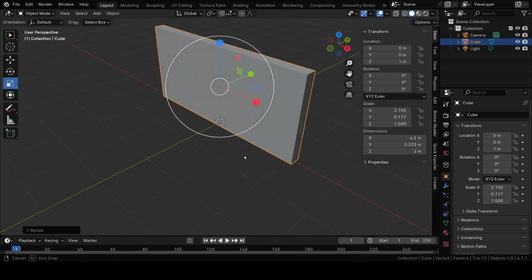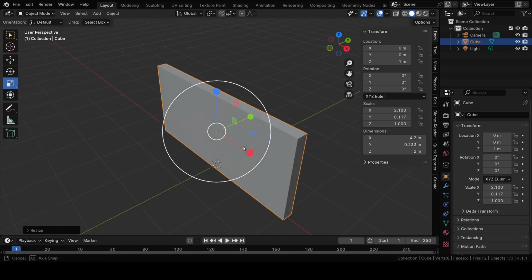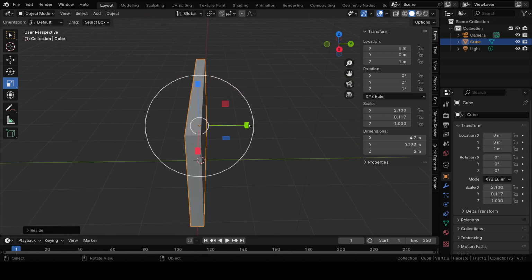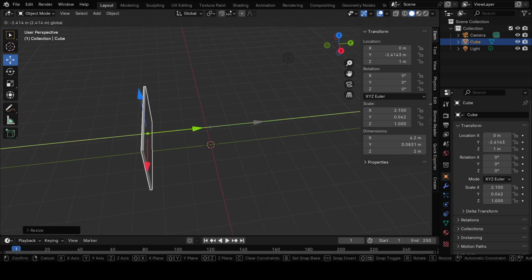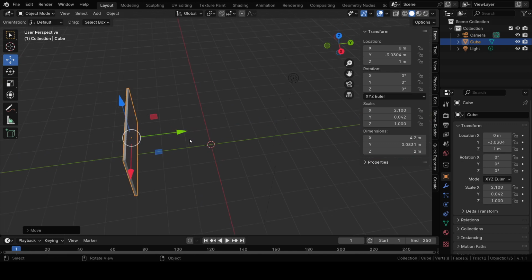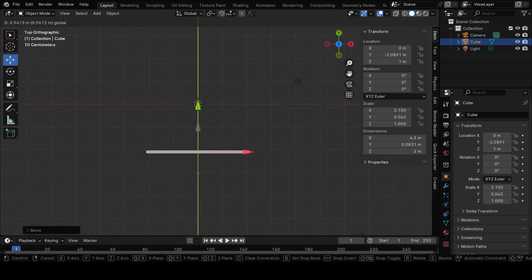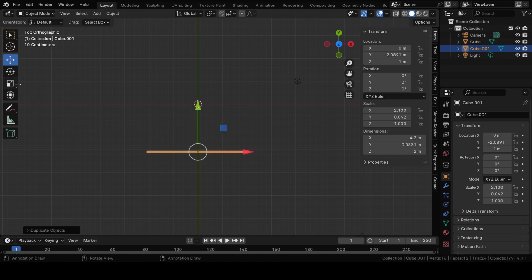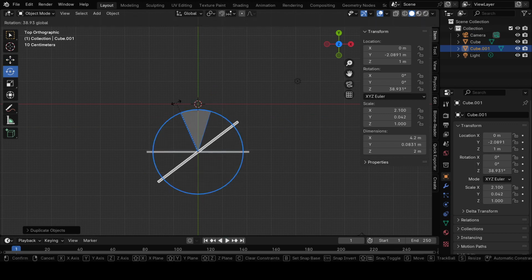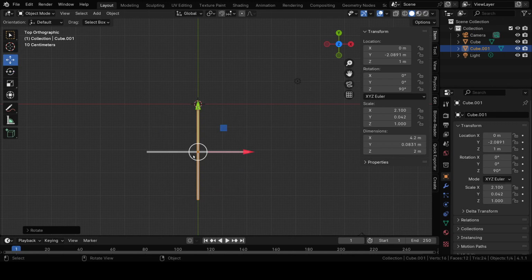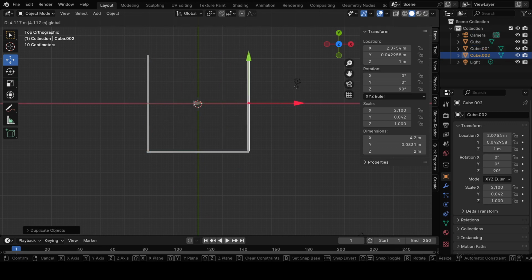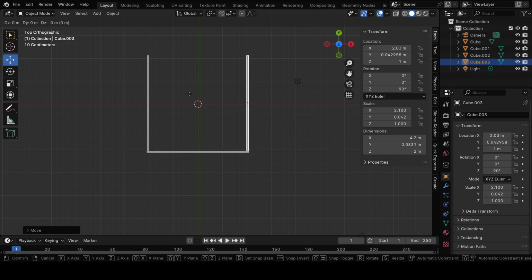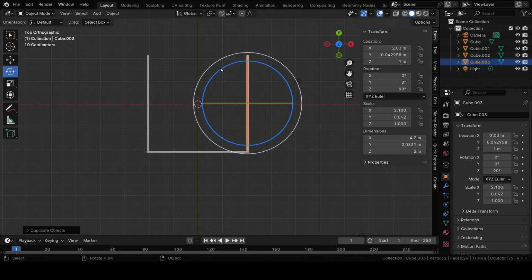See, like this, I have made one wall. You know how to scale it and all, right? Next, from the top view, I have to keep the wall here, and then duplicate with Shift D, rotate it, and keep one more wall here, and again Shift D, one more wall on the right side. So four cubes, four walls, that's all, very easy.